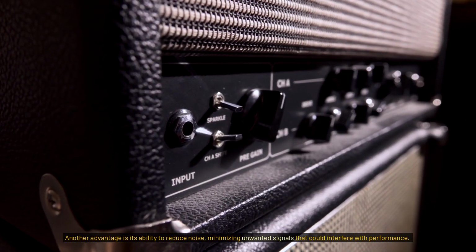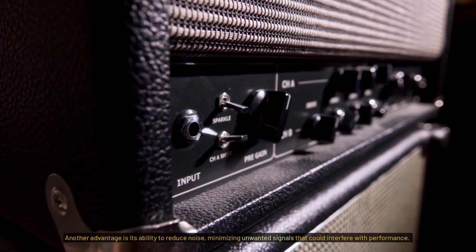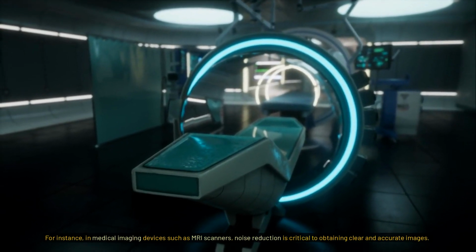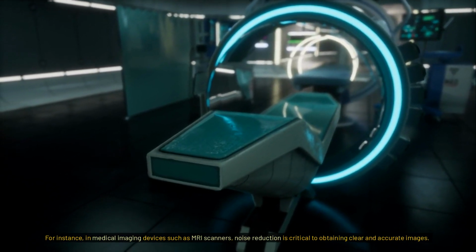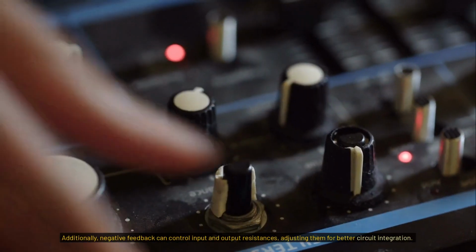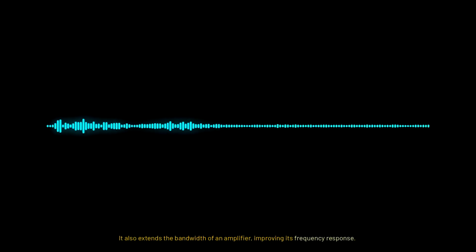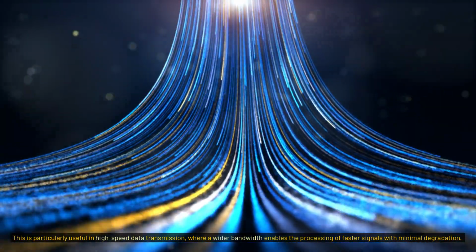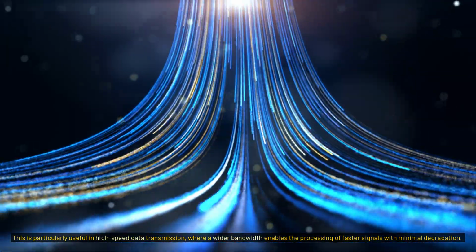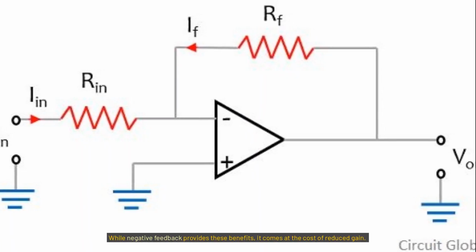Another advantage is its ability to reduce noise, minimizing unwanted signals that could interfere with performance. For instance, in medical imaging devices such as MRI scanners, noise reduction is critical to obtaining clear and accurate images. Additionally, negative feedback can control input and output resistances, adjusting them for better circuit integration. It also extends the bandwidth of an amplifier, improving its frequency response. This is particularly useful in high-speed data transmission, where a wider bandwidth enables the processing of faster signals with minimal degradation. While negative feedback provides these benefits, it comes at the cost of reduced gain.